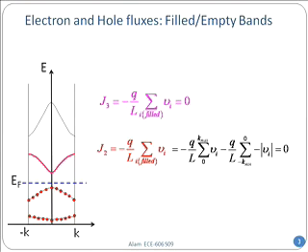It is like going from Chicago to Lafayette. Let's say both lanes have cars going in the opposite direction; with two ways, there could be no net flux going from one point to another. If there are no cars, which is band 3, or if there are an equal number of cars going in the opposite direction, then it is again zero current. Two quick points. This argument requires that the number of states I have in the plus k lane and the number of states I have in the minus k lane are exactly the same.